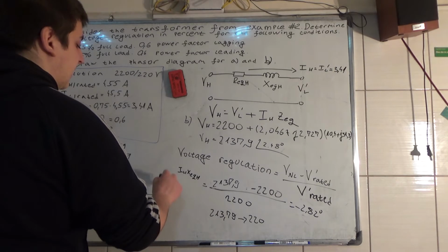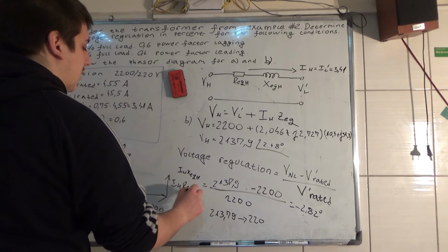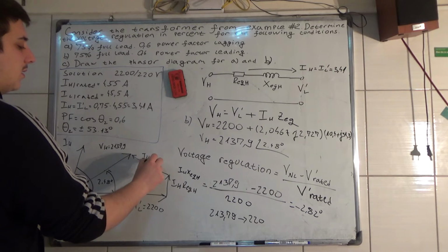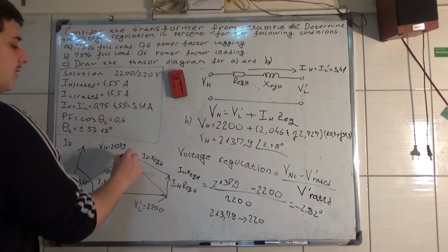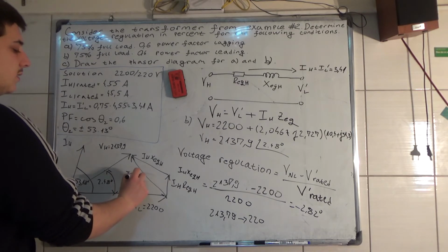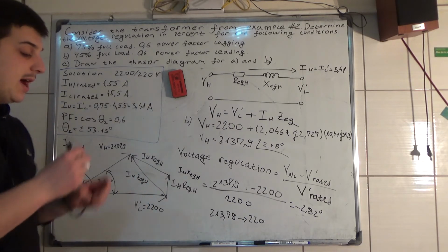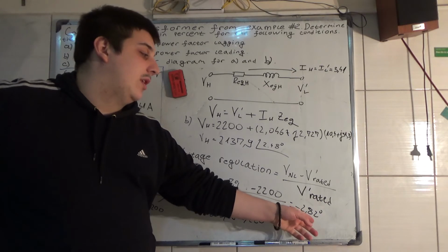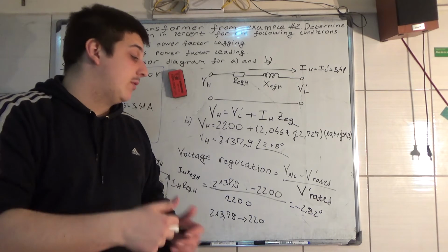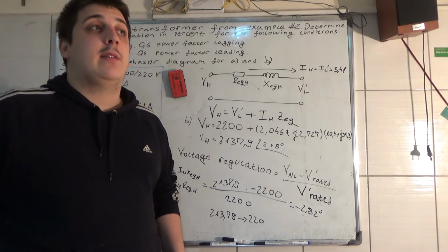Now you have a resistive load, a reactive, and the equivalent impedance. So minus 2.82 degrees. That means you have power factor leading, and then the voltage will rise on the output if you connect a load.